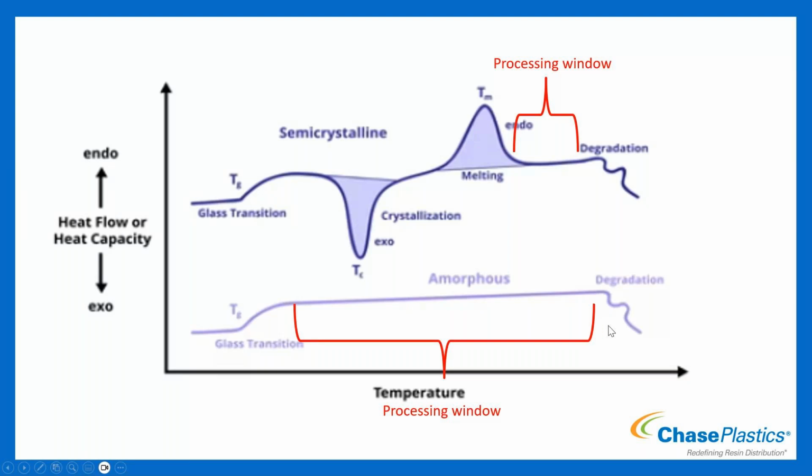So when we give you a recommendation for either of these, but specifically your semicrystalline materials, if we're saying, hey, here's the processing temperature for this material, it's a good idea to be pretty dang close to it, because if you go much hotter, you're introducing a little more shear heat, whatever it may be, you're getting real close to degrading the material. And so when we say a sharp melting point, here it is, there's your processing window, versus a gradual softening that we can then process within.